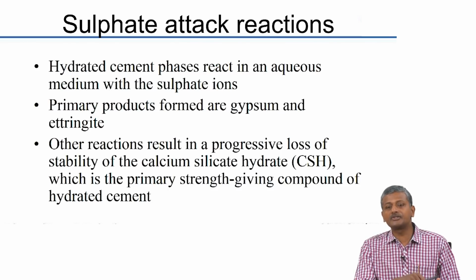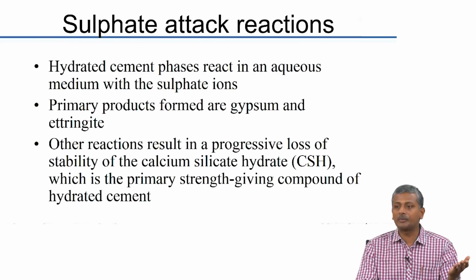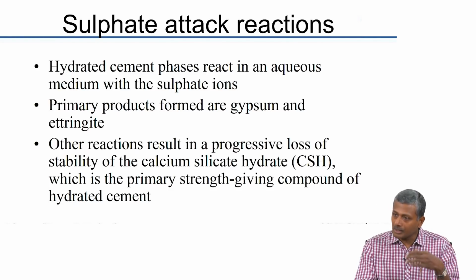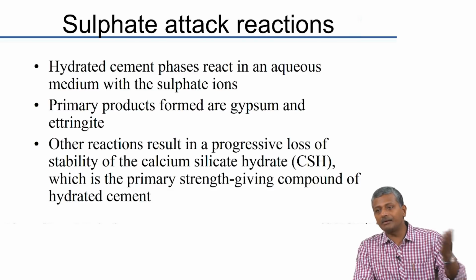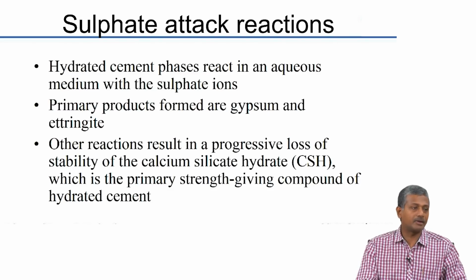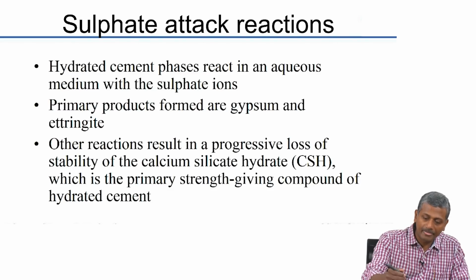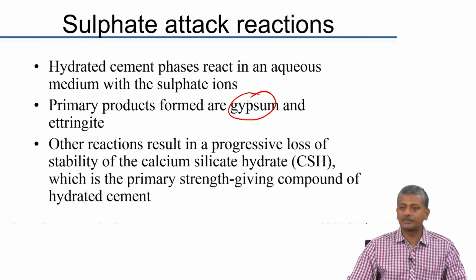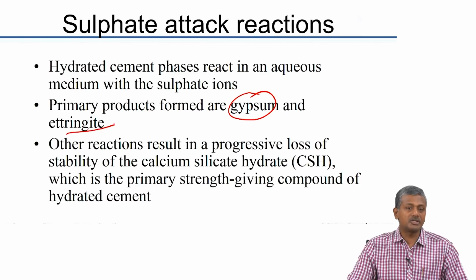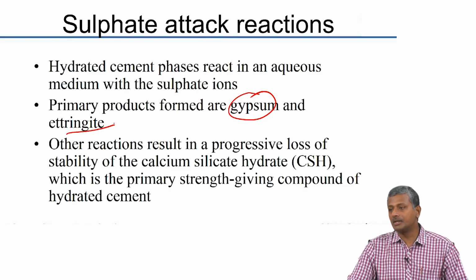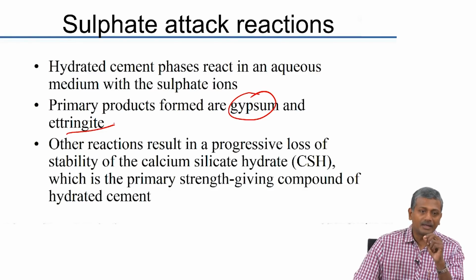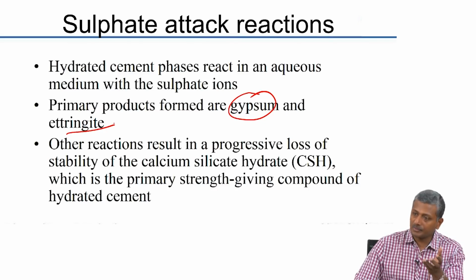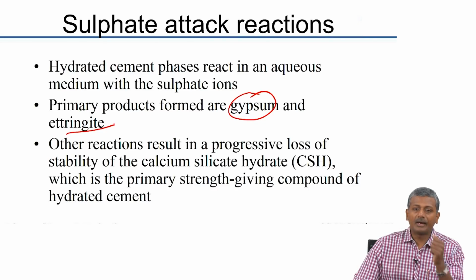So, you have the remnants of C3A and tricalcium aluminate hydrates along with monosulphate that can then react with this gypsum to reform ettringite. So, gypsum forms first and then combines with the aluminate sources to form ettringite. So, again gypsum formation itself has been associated with some level of damage, primarily because gypsum is much softer than CSH or calcium hydroxide for that matter. Okay. And ettringite formation primarily causes expansion that leads to damage in the matrix.